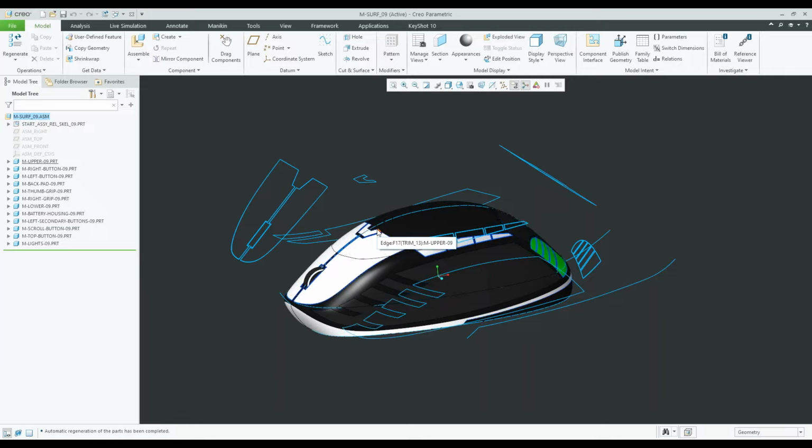So it's kind of like just a hidden part that controls your features. Yeah, you could even just create a normal part and then create the same planes, axes, and sketches that I create within a skeleton part in a normal part. You can do that as well. So I guess it's just your preference there.